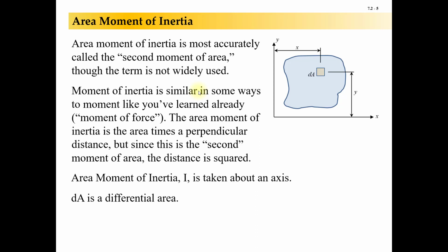The cool thing is that once you know how to calculate this, you can apply it to those other versions of moment of inertia really easily. All right, now moment of inertia is similar in some ways to the moment that you've already been working with in this class. We call it moment, right? Those curvy vectors are actually the moment of force. We call it the moment of force. Moment in engineering means taking something and multiplying it by a perpendicular distance. So a moment of force, we're taking that force and multiplying it by a perpendicular distance, and that would be the tendency for rotation, the moment of the force.